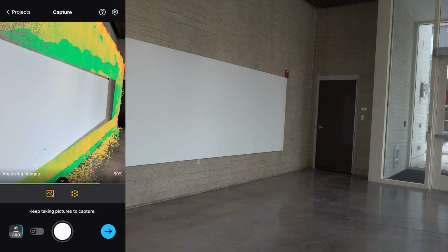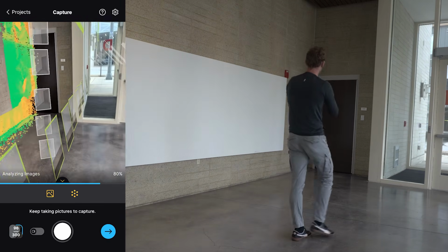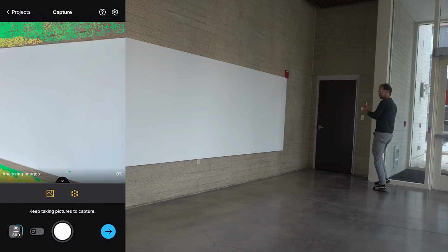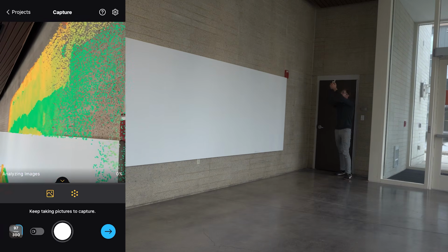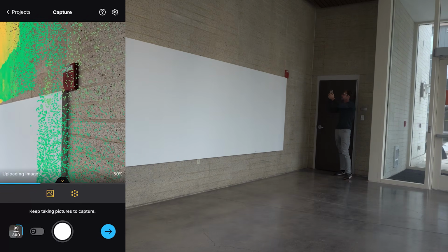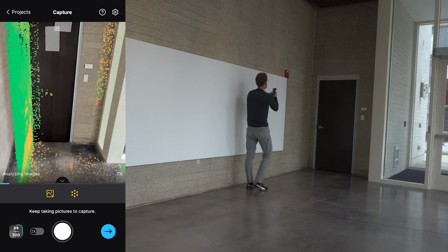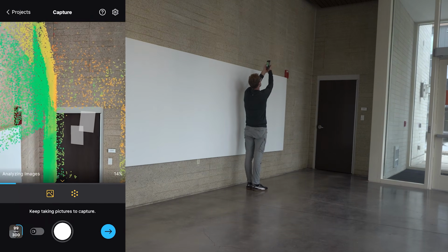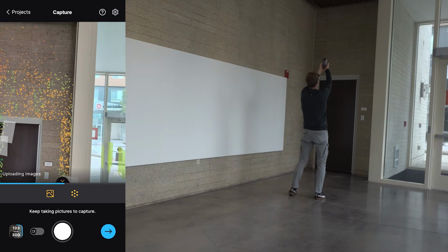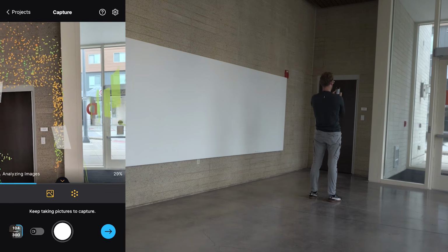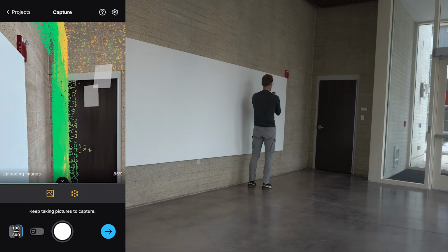It's also a good idea to get a few oblique angles of the wall for photogrammetry. So I'll take an angle like this, and then I'll also come around this way and take an angled wall photo. This helps RealityScan get the depth it needs. It will also help to get the fire alarm here. Now I want this to be parallel to this wall and move parallel to it, creating parallax. I'm not going to worry about that glass section. I'm just trying to get the corner of the room right here.